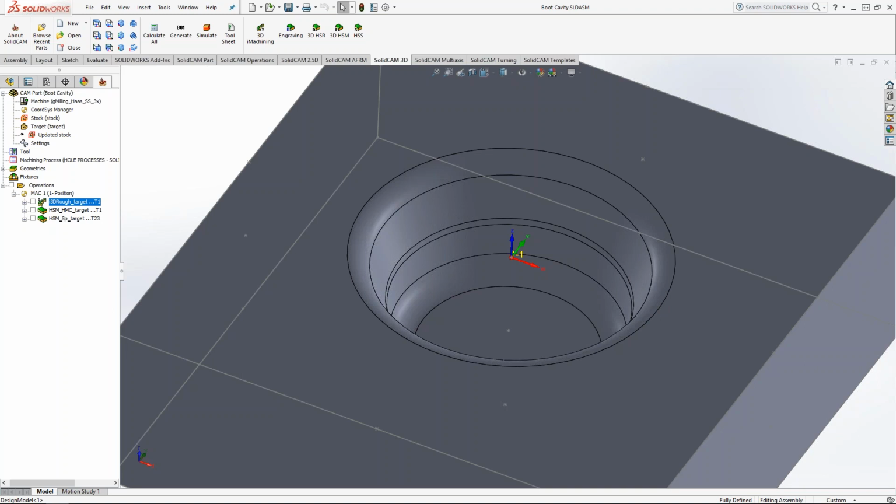So really the AlTiN coating thrived with the heat that was generated with the surface speed that I was running. Most of these carbide tools I would run somewhere in the neighborhood of 600 to maybe 750 surface feet per minute. With a half-inch end mill, that's somewhere between maybe 4,700 RPM to 7,500 RPM.